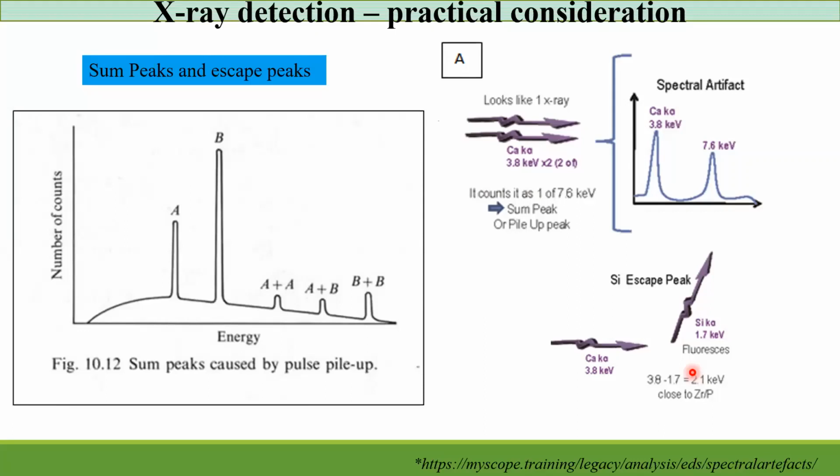And if you don't have the possibility of stating the real percentage, say it openly, but say honestly why: because you may get a silicon peak. In addition, you may get a copper peak from the copper grid. You may get another peak from the carbon tape if you are using SEM, and even copper from copper tape. So there are many possibilities of artifacts.